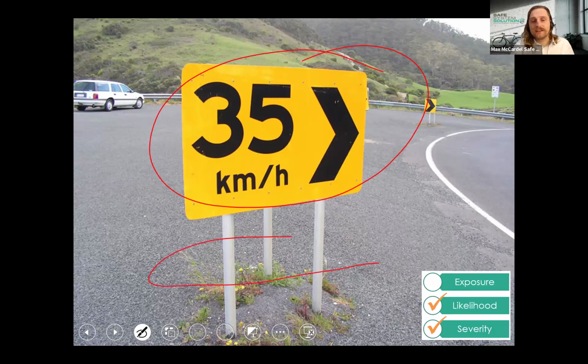Also, interestingly, in this example, they've used a different type of post that is not just like a metal post. These are actually frangible. They break away. So if motorcyclists were to come off at this curve, they could break through that sign and not have another fixed hazard close to that edge of the roadway that they could collide with.